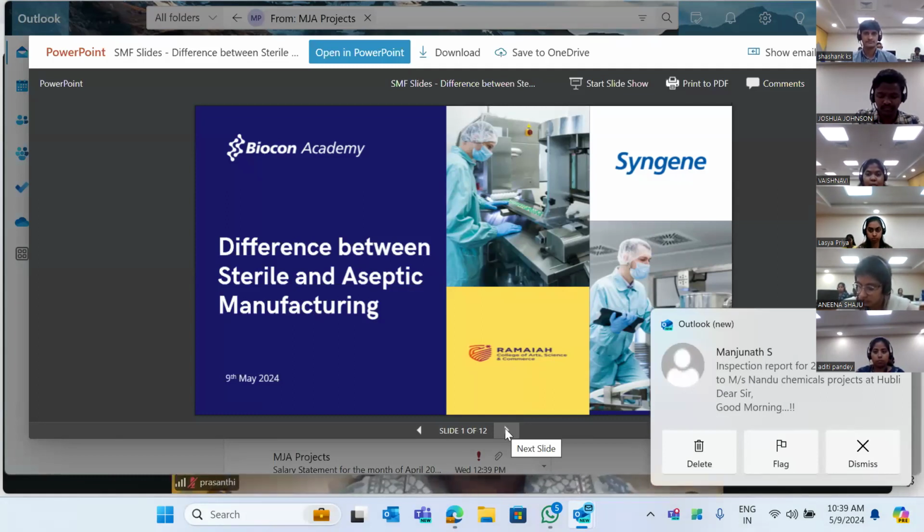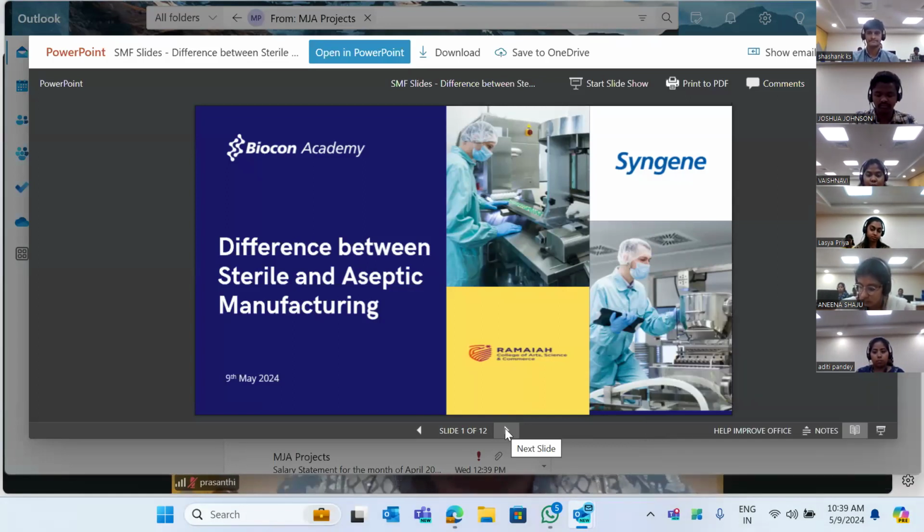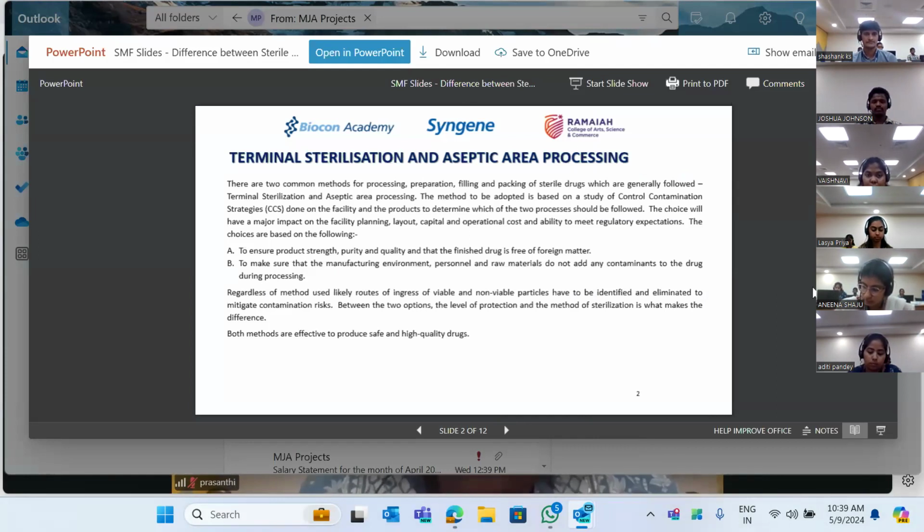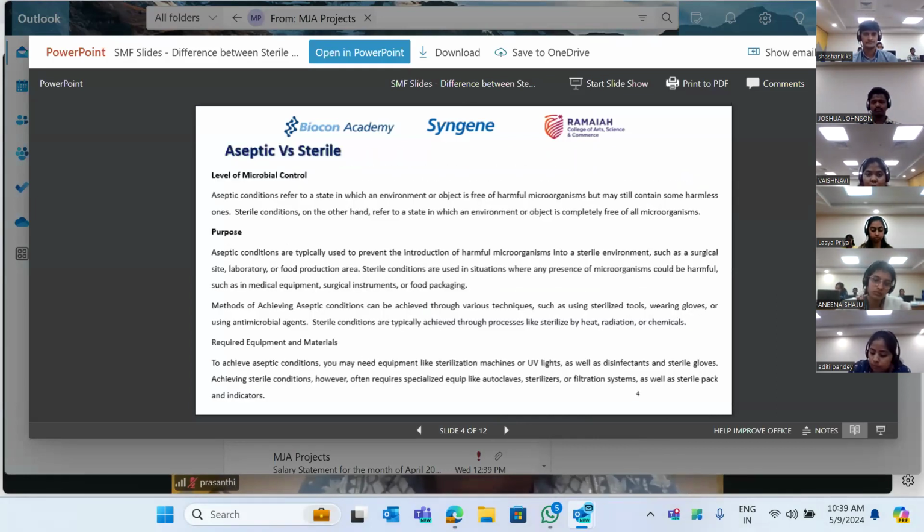So now the last topic, my topic, was on the aseptic and sterile manufacturing. What is the difference between aseptic and sterile manufacturing? The basic difference is aseptic manufacturing involves preventing microbial contamination during the production of sterile products by using clean room barriers like LAF or RABs, that is restricted access barrier systems, and sterilized equipments.